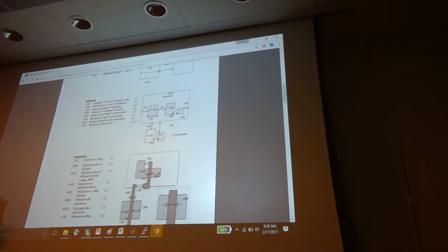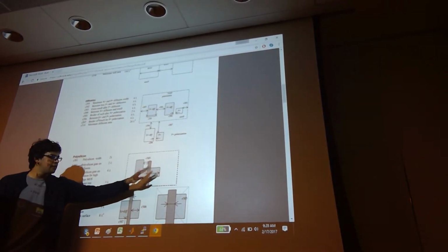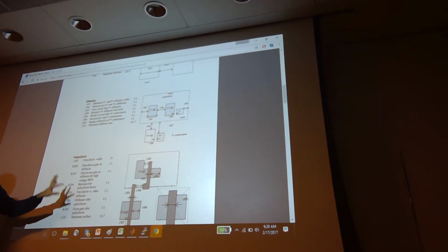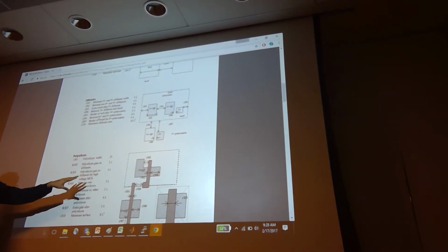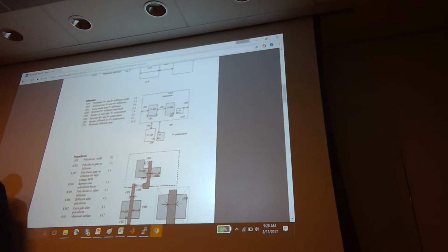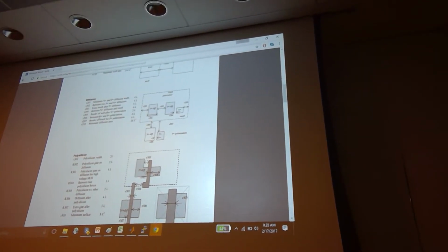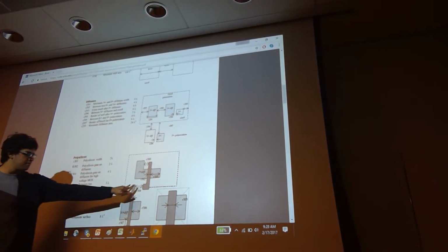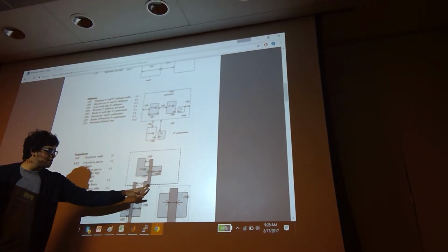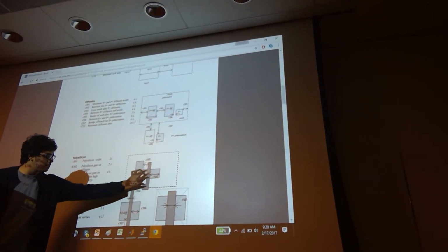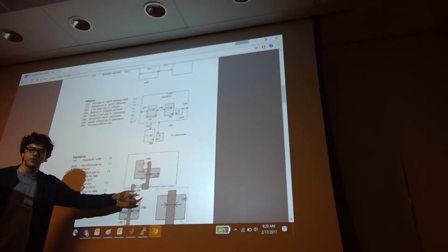If you have a doubt about how much spacing you need to leave here or something, just refer to this material, figure out what the dimension has to be, and just follow this dimension. Wait, R304, are they purposely extending the polysilicon to the left? Yeah. If you decide to make this sort of a design, then you need to follow this rule.